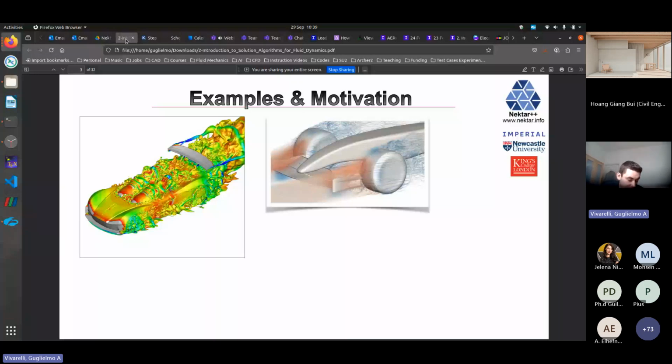And you can see that you've got your large scales, that contain the largest kind of energy, and then of course the smaller ones, which are more difficult to deal with because you're going to have to resolve them, because otherwise energy accumulates in your solution and diverges, because we're not yet at the point where we can resolve everything in quasi DNS range, or DNS range if you prefer. And therefore energy tends to build up in the small scales and cause divergence.